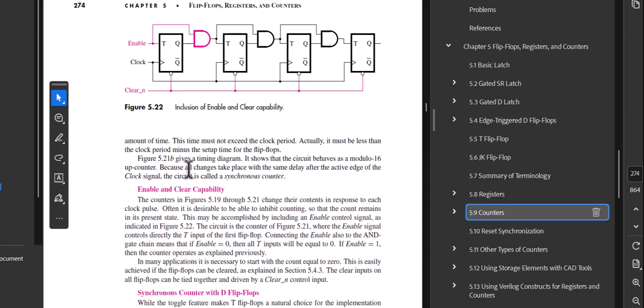And then from here on out, if the first flip-flop is 0, then it's not going to change. And so if it doesn't change and the enable is 0, then you're going to have 0 going into the second flip-flop as well. And then from then on, you'd have 0 going into all the T flip-flops so that they would just stay where they were.